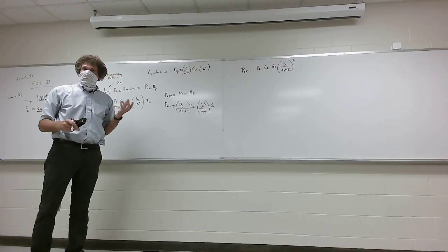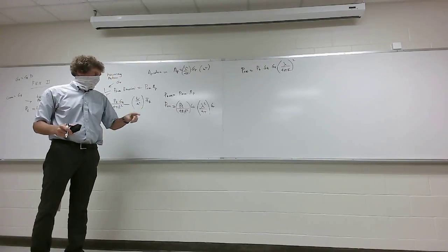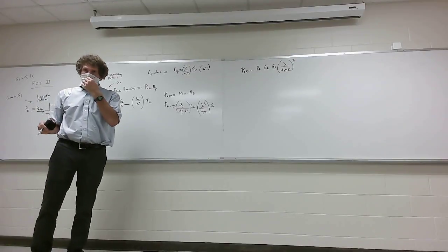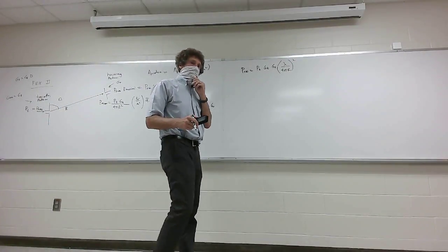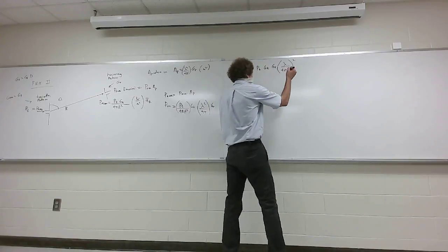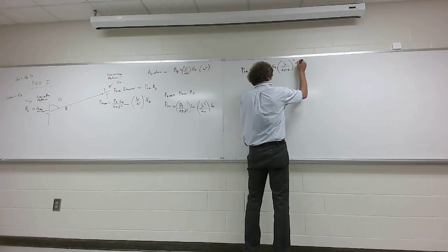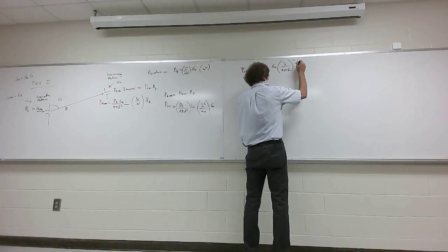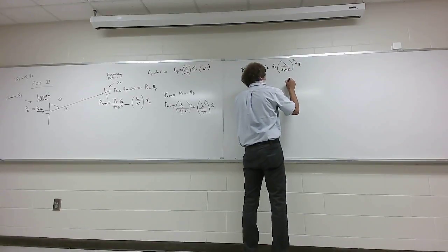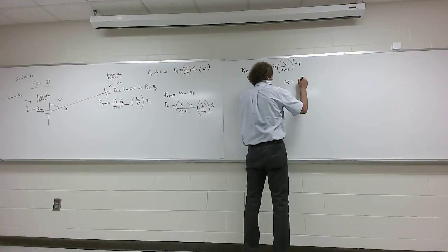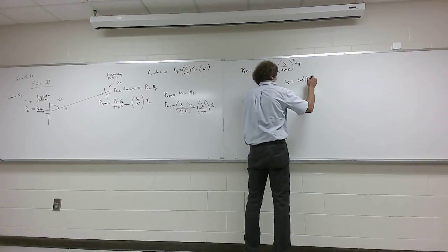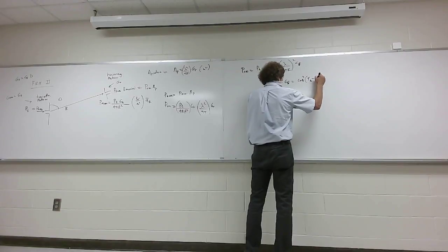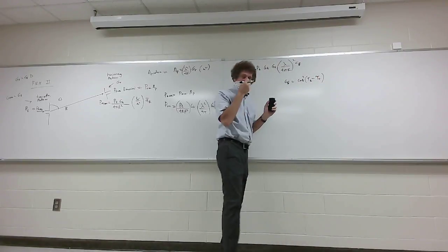Y'all see it, class? Group the 4 pi's, group r, group lambda, and square it. Now, there's one thing, and this is what you see in Dr. Winter's book. I suggest you put this in. This is also times the polarization efficiency, EP or E, I think he has EF in the book. And EF is really going to be the cosine squared of the difference in the tilt angles between the transmitter and the receiver. We went through that last time.